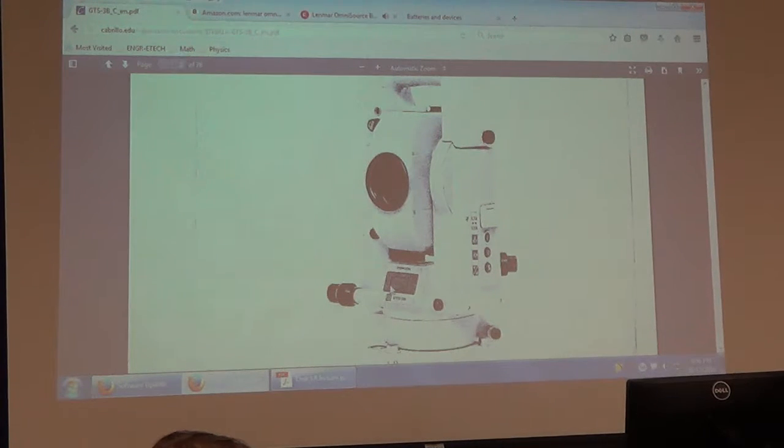So did you put a plumb bob on the bottom of it? Remember we talked about that in class? Putting a plumb bob on the bottom of the theodolite to see if you are in range. So I would try to level the tripod and then get the equipment all leveled, then put the plumb bob on, and then you're within an inch of the tack, and then you just loosen it and move it around until you're over. And then once you seem like you're over, that's when you look in the optical plumb.